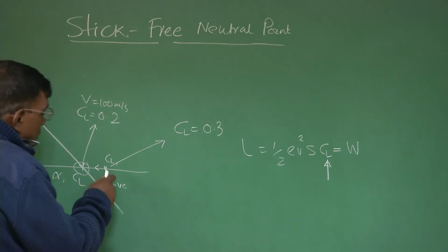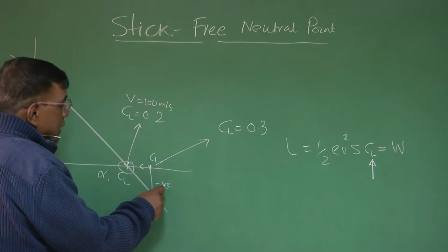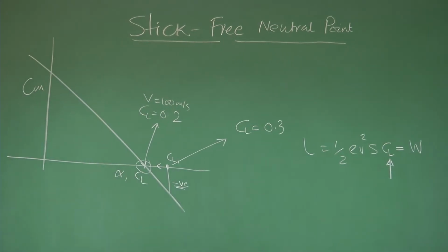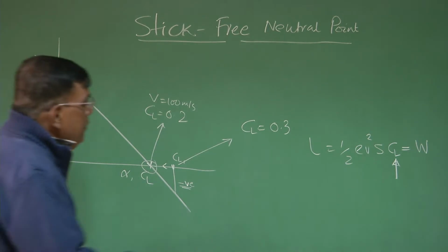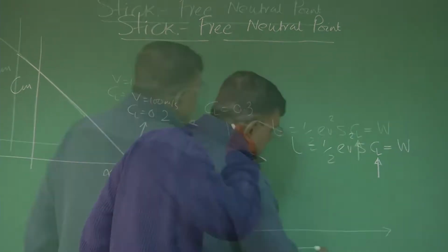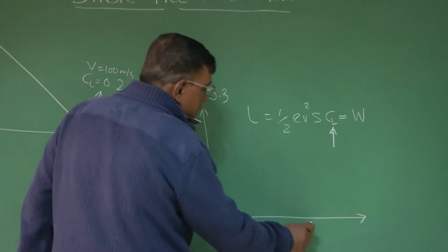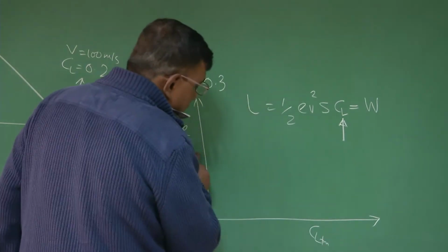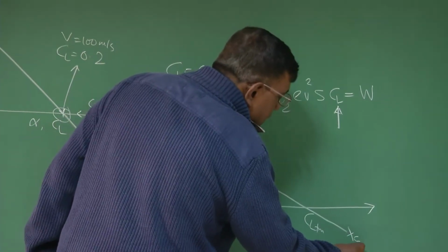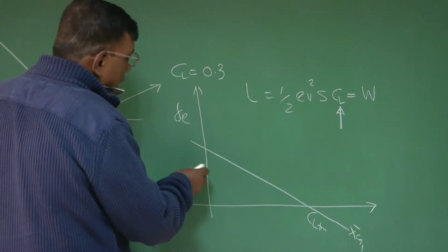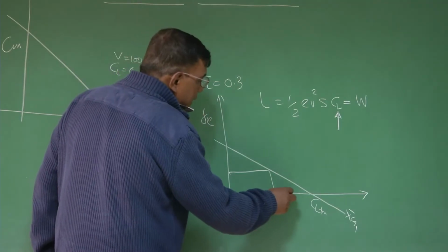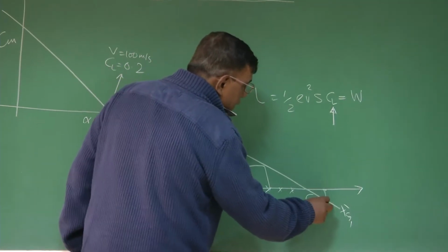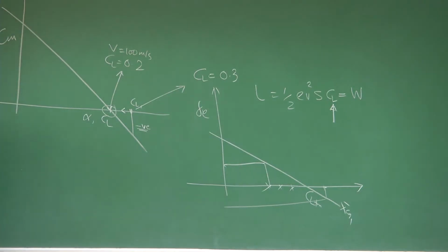And you also know that if I want to fly at this CL1, it will generate a negative moment. So, I have to generate a positive moment by giving elevator deflection, right? And that is why, if you see this graph, delta E versus CL trim for a given CG location, XG1, you have a definite value of elevator deflection required if you want to fly at this CL, at this CL, at this CL, or at this CL. You have a different value of delta E required.